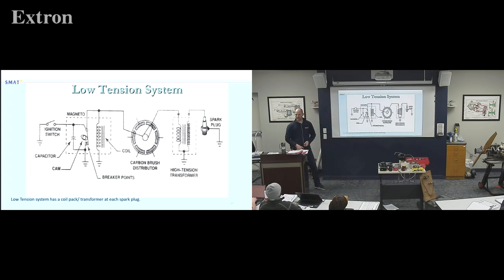Is that a 100 factor, 240, add 2 zeros, 24,000? Double check. 240. Yeah, that's correct. So our ignition coils are basically a 100 to 1 wind ratio in our magnetos.